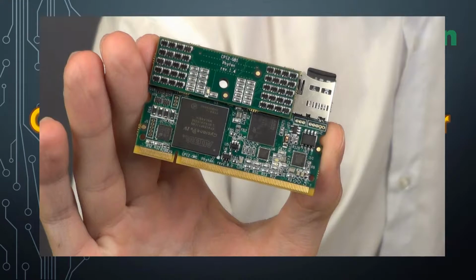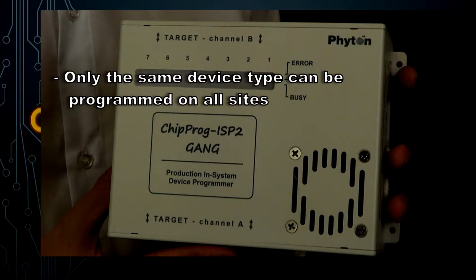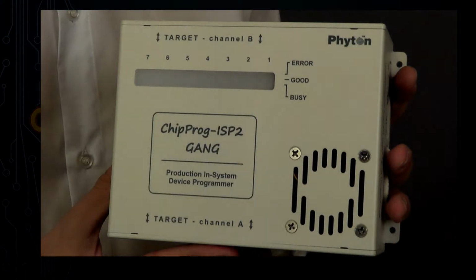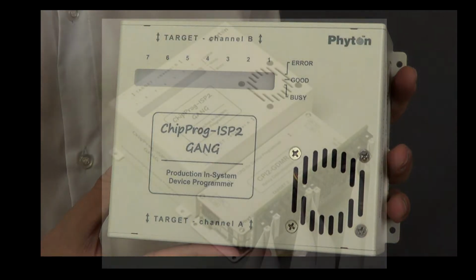The gang programming mode, if it's controlled from the CPI2-Go2 graphical user interface, has the following fundamental restrictions. Only the same device type can be programmed on all sites. All the sites must share data loaded in the same buffer. Only the same auto-programming batch of commands can be executed on all sites. Let me emphasize that these restrictions relate to the GUI control mode only. Use of a standalone mode, or an application control interface, or a command-line control mode enables you to bypass these restrictions.